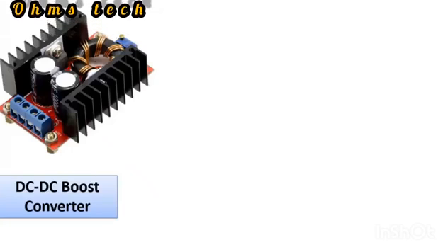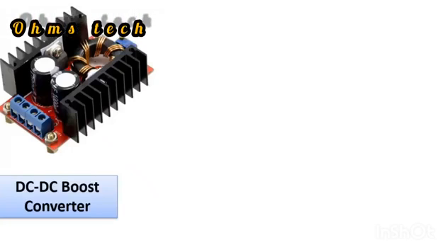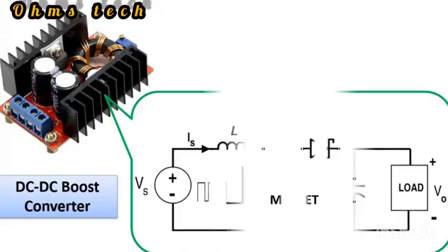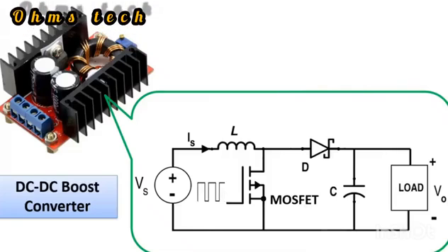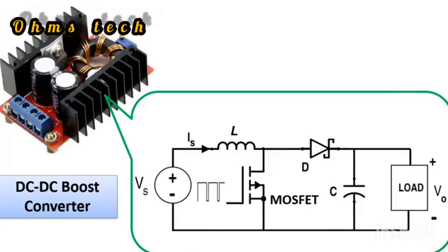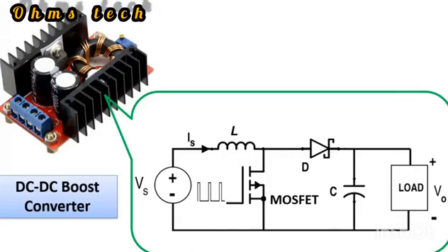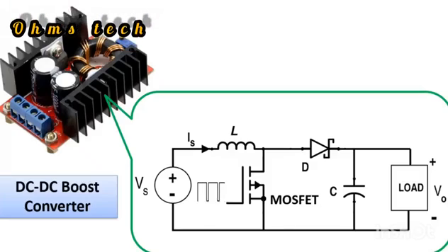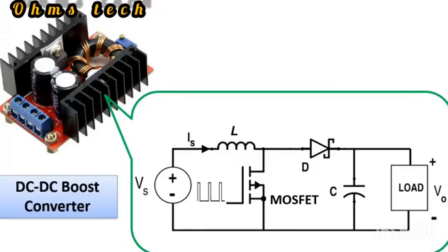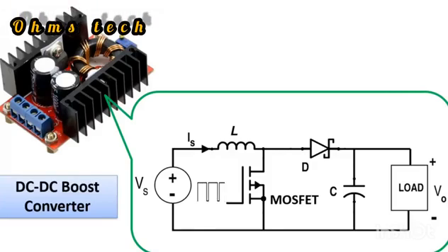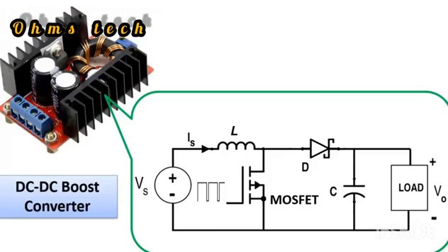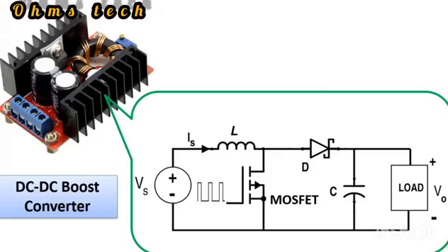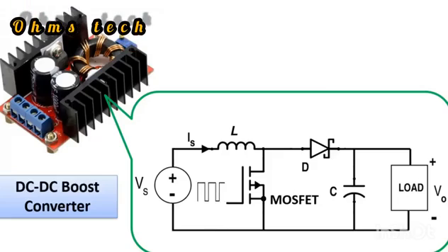For example, you see a DC to DC boost converter here. The circuit diagram for this is basically the same as here. The amplification process is according to the switching speed of the MOSFET located here. Triggers are made at high frequency values at the kilohertz level. In this way, MOSFETs and Schottky diodes are preferred instead of normal silicon diodes in order to obtain healthier results and respond to high-frequency switching speeds in converter circuits.